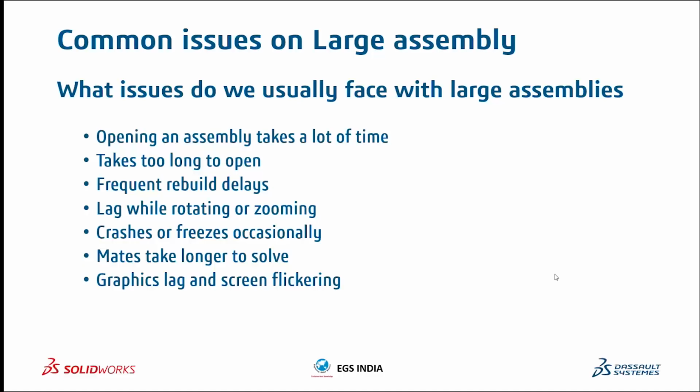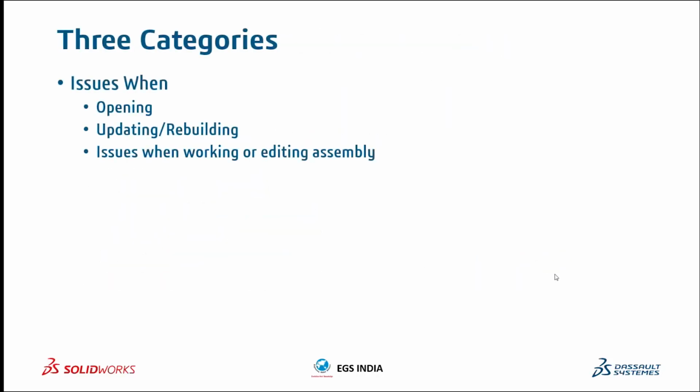To explain this vast number of opportunities for you, we're first going to filter it into three categories. I'm going to classify these issues into three categories. One, issues when you're opening a file. Let's say the assembly is taking a lot of time to open, or is getting stuck when it's trying to open, or SolidWorks closes when it's trying to open. The next category is when it's updating or rebuilding. Let's say you make a small design change, change a small dimension, or create a new mate, but the assembly takes too long to respond. That is the second part.